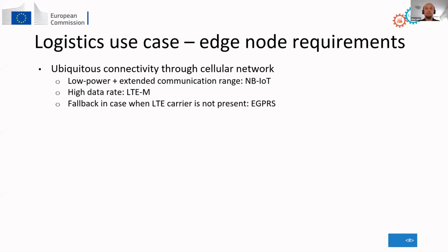So we need to use some communication technology with higher data rates. For example, if we want to update the firmware image over the air, we should use something with a higher data rate, and LTE-M is machine-to-machine technology which belongs to the scope of LTE, as well as the NB-IoT, and provides the higher data rate.